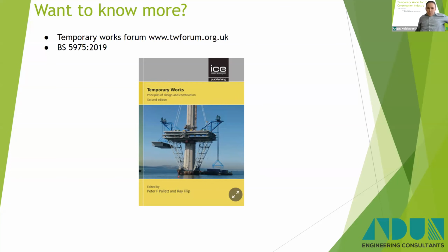Please could you reiterate what you'd expect the process for a Cat 3 check to be? So I would expect the design to be completed, and then I would expect the drawings only and supporting information to be provided to the Cat 3 checker for them to undertake a Cat 3 check. It's okay to pass on a design statement that outlines how the designer has done the design, but not the actual physical numbers, the calculations. That's what the guidance says. A Cat 3 check is an independent set of calculations produced that verifies that the solution works. Hopefully that answers your question, Edward.